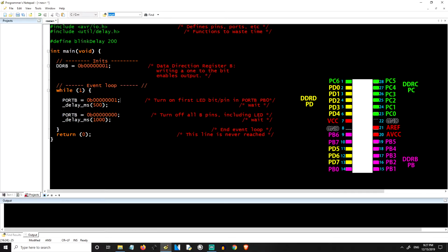So if you wanted to just do it a simpler way, you could have your predefined header file that labels all of these different pins in this diagram on port B, and you'll be able to do something like PB0 and then bit shift it with a 1 like that. So you see how much easier that is? I'll show you how to do that later on. It's pretty simple, and you're gonna really like it. So for now, we're just gonna leave it how it is.